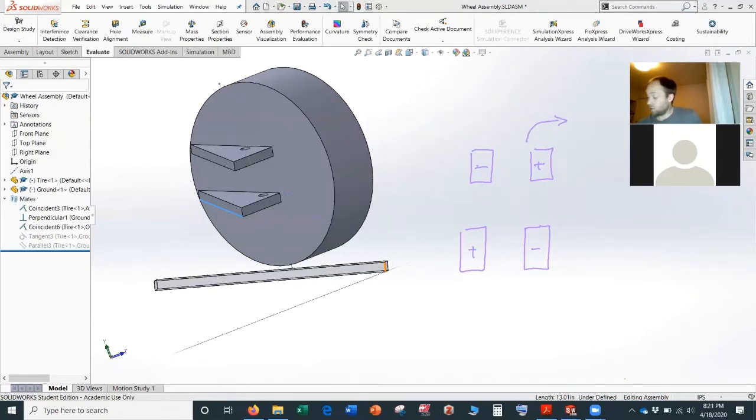is good to a point, because typically what that's going to do is shift weight forward and to the left, basically. And so this helps shift a little bit back to the right in the front where you need it. But you'll notice the downside is it gives you more weight shift in the rear. So it basically doubles the weight shift in the rear on a right-hand turn. This might be from the caster, this is from weight transfer. And in this case, this is from the caster, and this is from the weight transfer. So it cancels out some of the weight transfer in the front.